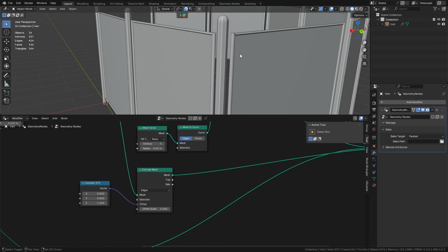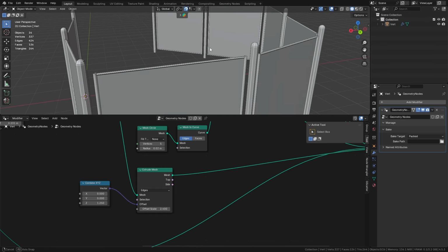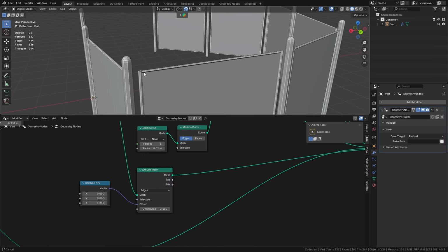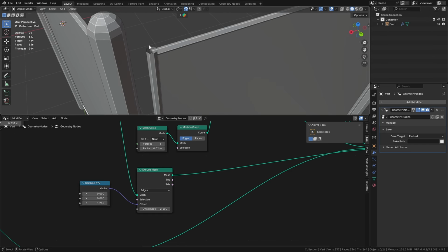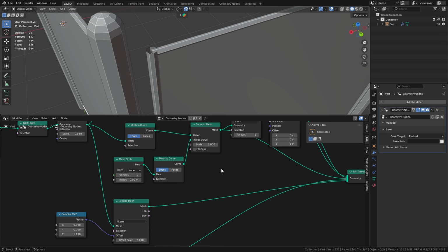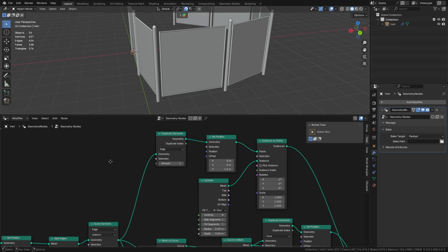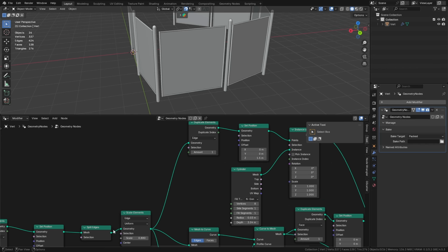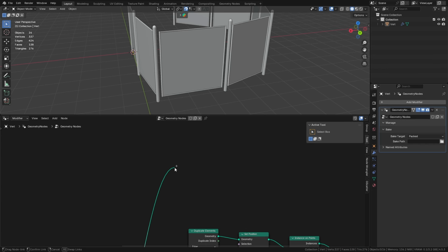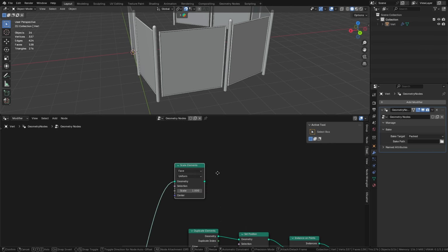Okay, let's now create the hinges that go between the main pole and the middle bevel. These cylinders have open caps. Let's add the caps to these. For the hinges, we're gonna use these split edges. Let's scale these again. This is going to be edges uniform, and let's put the scale to 0.93.